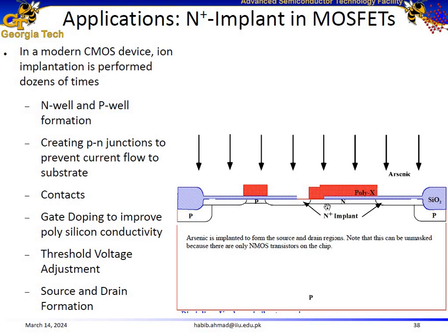The distance between the drain and the source is called the channel length, or it is also called the technology node, and it's really crucial in technologies as well, because our technologies in processors and memories are based on complementary metal oxide semiconductors, in which we have p-type MOSFETs and n-type MOSFETs placed side by side.